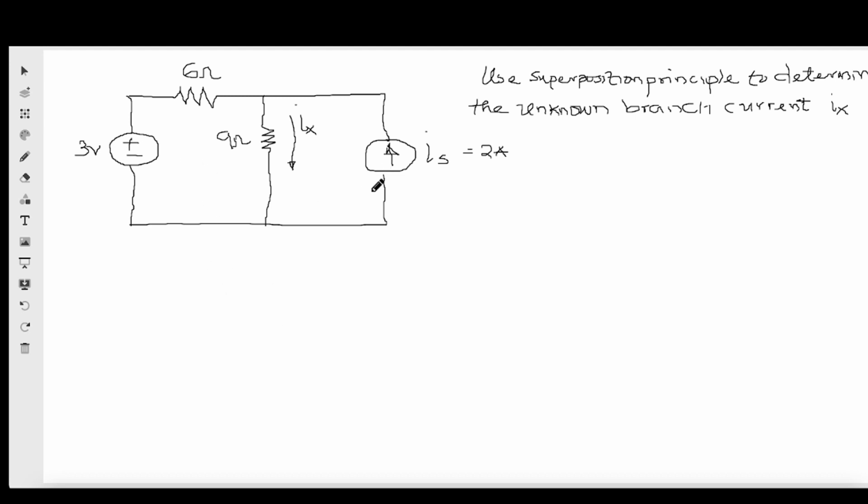So which means that we have to separate these independent sources, right? So we have to separate this, we have to separate this. So if I draw two circuits to show that, which means that if we are removing the current source, let me write it down. If you are removing the current source, you open it, right? When you remove the current source, you are opening because current is not flowing again, so it has to be an open circuit. So we open circuit current source.